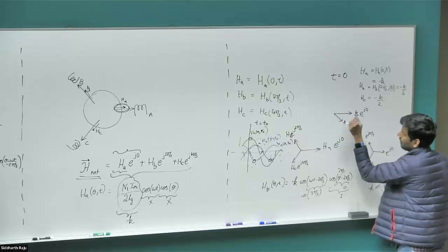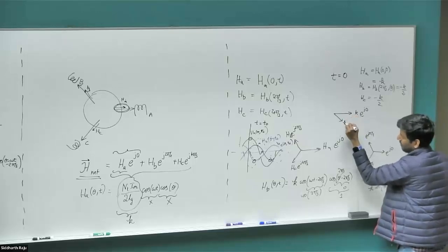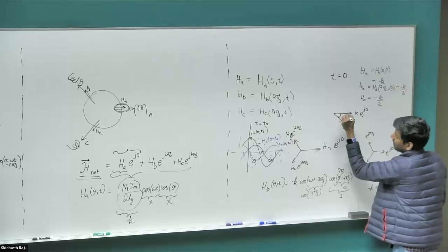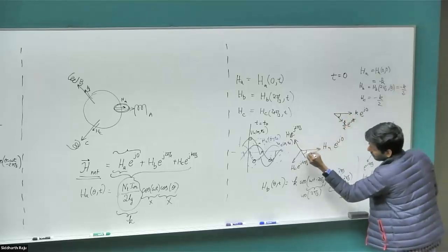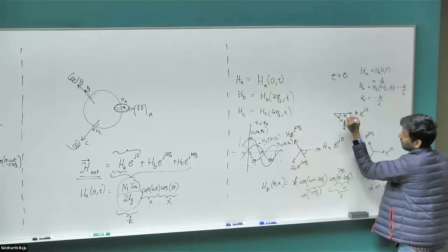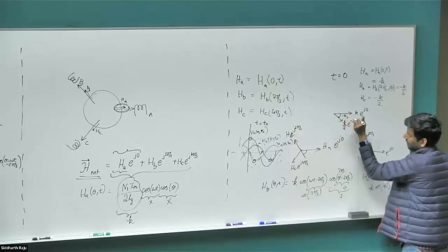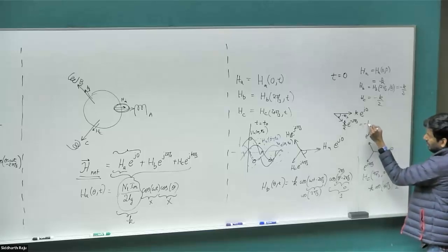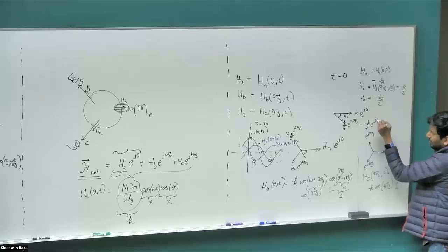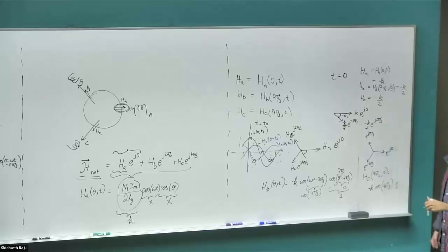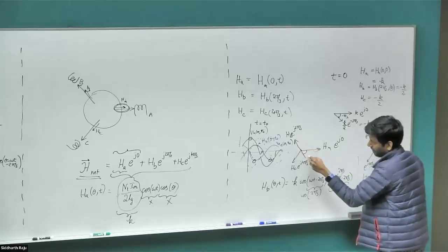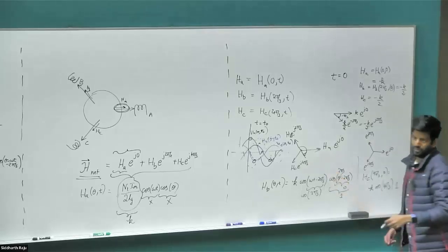So this would be k times e power j0 for A phase, k divided by 2 times e power j. This angle is going to be 60 degrees, negative pi by 3. e power negative j pi by 3. So this is the same as saying negative k by 2 times e power j 2 pi by 3, right? If I had a vector of negative magnitude along this direction, that is the same as saying the vector is along this direction with a positive magnitude, just 180 degrees in the opposite direction.